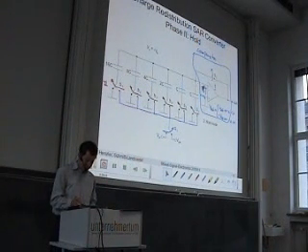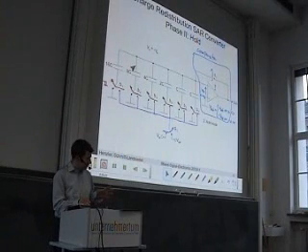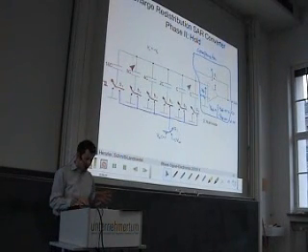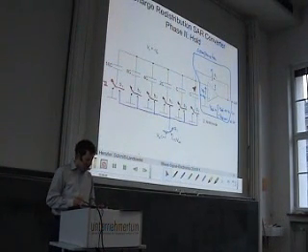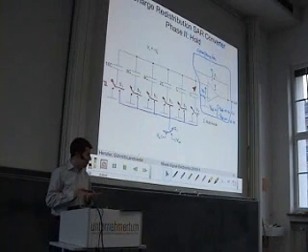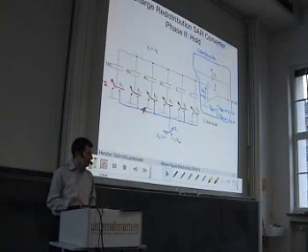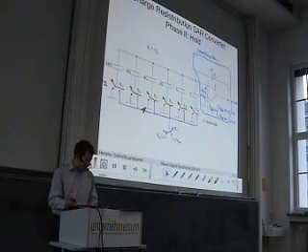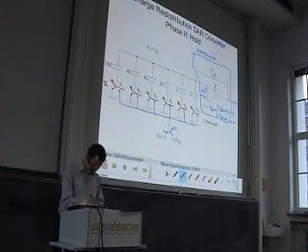There is this high impedance input into the op-amp, no charge can escape here. So there is the possibility that you mentioned that charge is transferred from one cap to the other, but charge is not leaving the array. And there is also no charge transfer currently between the caps, because they are still all in parallel. They are connected to this node X, and they see the analog ground on all other nodes. So the total charge on the caps cannot change.